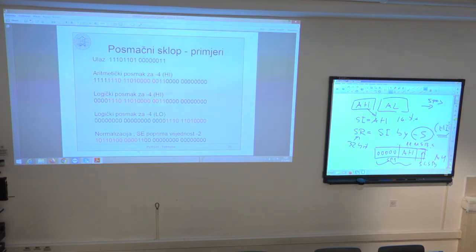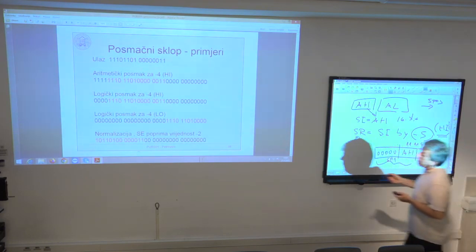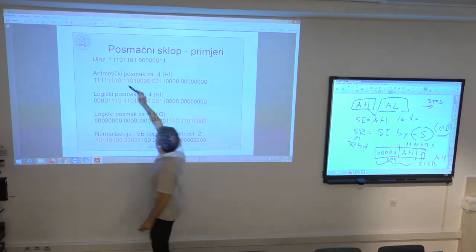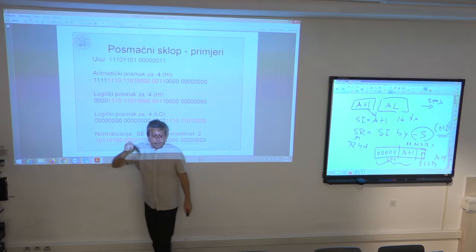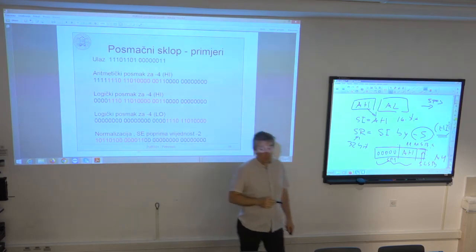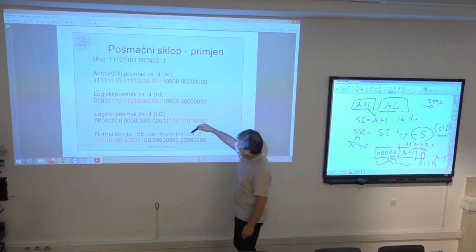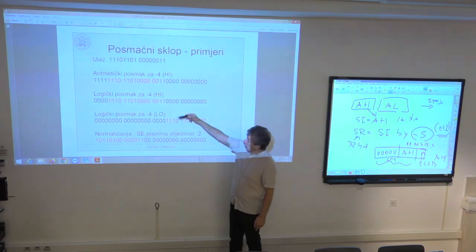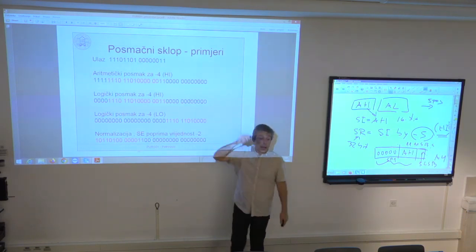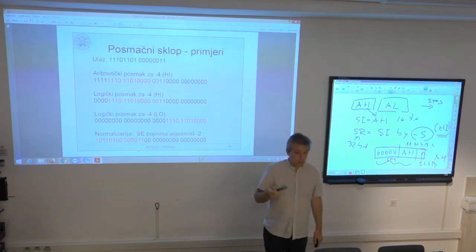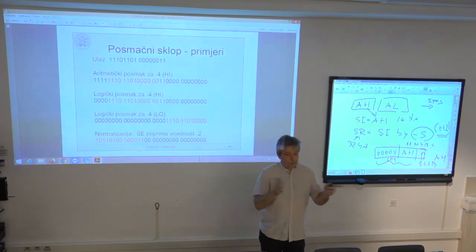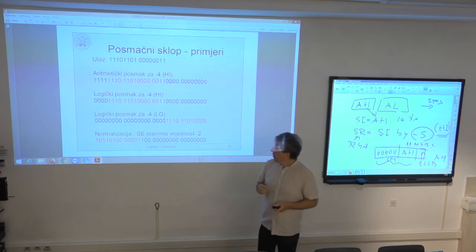So I actually want to count how many leading ones I have, or how many leading zeros I have if the value is positive. In this case here, the result of this normalization would be -2, because I have 2 extra ones. So theoretically, I could shift it to the left by 2 positions, and only then the value is normalized. Okay, the number is negative.